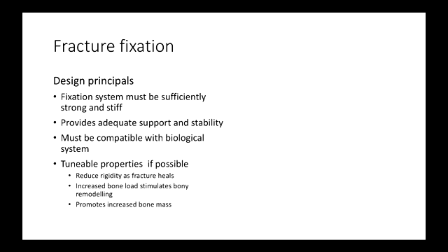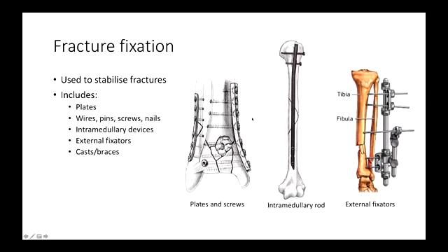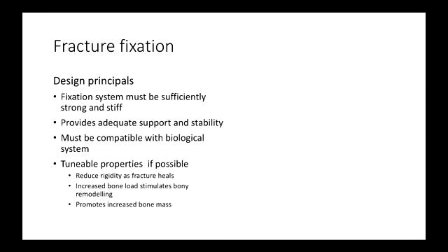Right when the bone is fractured, we don't want it to carry any load. We want the plates or the external fixators to carry all the load. But then as the bone starts to heal, we want to offload some of that load through the fixator to the bone, because load on the bone stimulates bone growth. So that's the really neat thing with the external fixators. You can reduce how much support it's providing as the bone heals and takes more load.